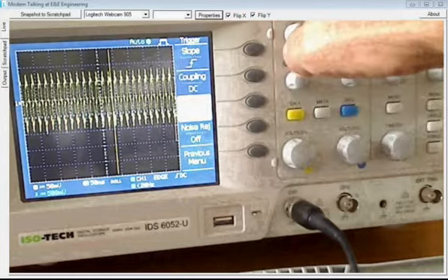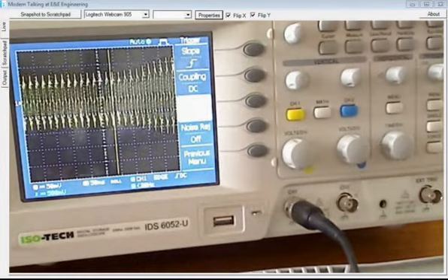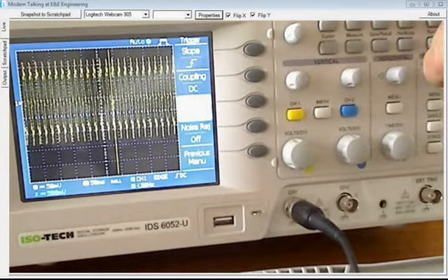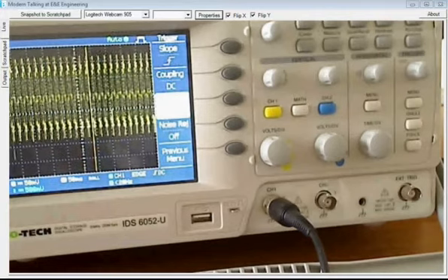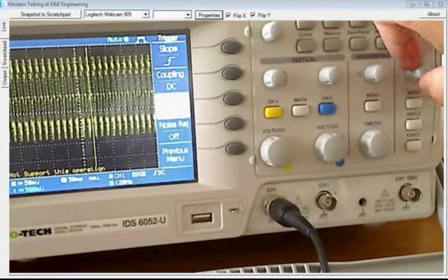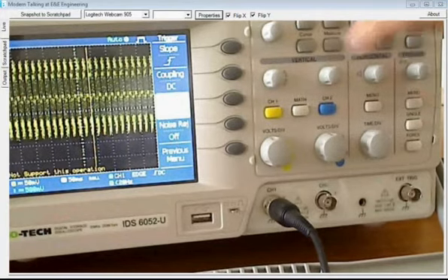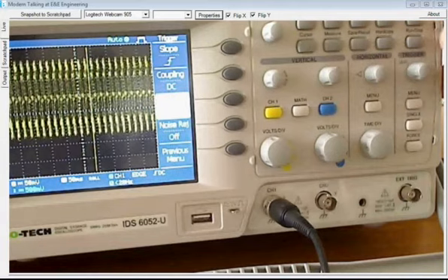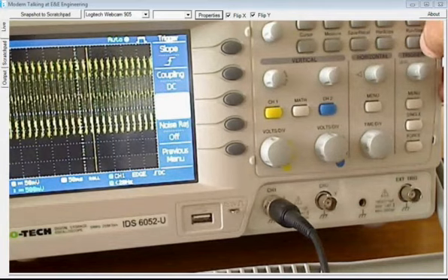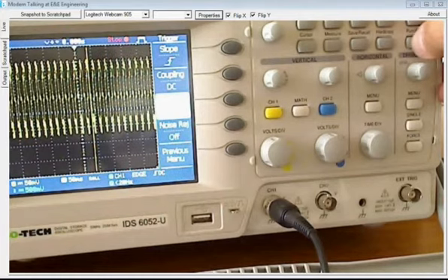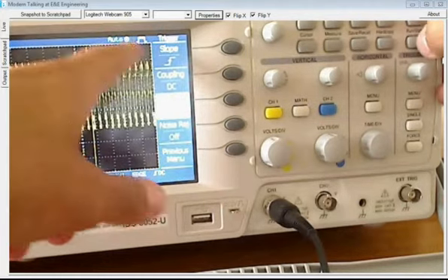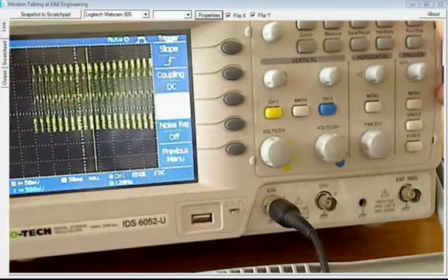And then the other thing that I want to set here is just your trigger level. So this tells you what is the voltage that you want an activity to be triggered at. So if I change, not supported, that's not good. Let's just quickly. Yeah, there's something else you need to know. If you want to trigger, you can select between auto trigger and manual trigger.